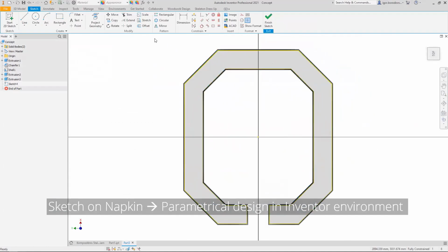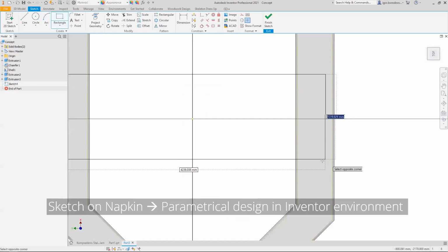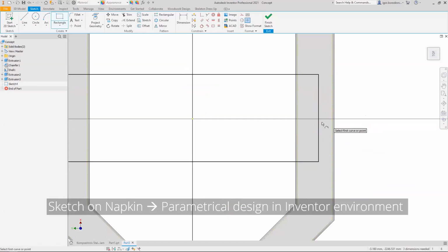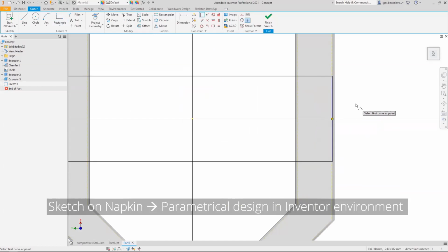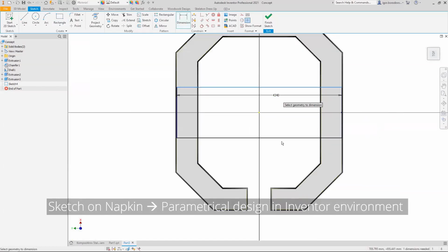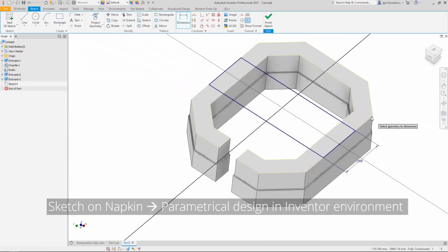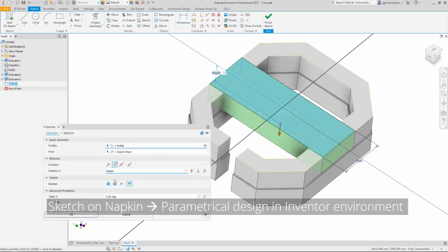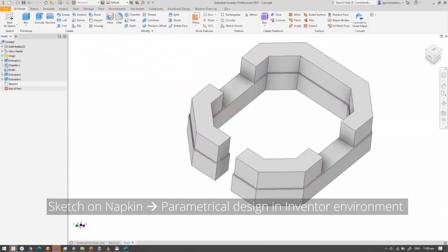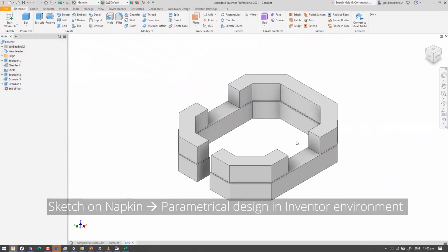As you can see, I'm using the multi-body design methodology, which means that when I do an extrusion operation, I set this as a new solid body, and this will allow me to have better control because I can split the top portion, which is like a glass frame, from the bottom portion, which is like a panel component. After all, we spent just maybe 3 minutes or so, and that's how our concept is looking.